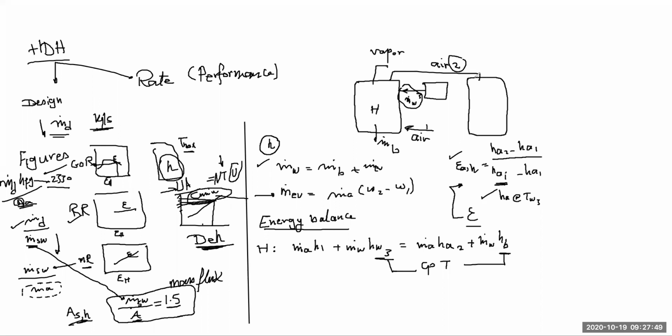The same thing can be done if, for example, I do not provide you with the T water leaving here, but rather ask you to calculate this value. Maybe you can calculate H water out from here and then substitute into this equation to get H of the brine. That is something that can be done in problems, so that each time, in one equation, you have only one unknown.